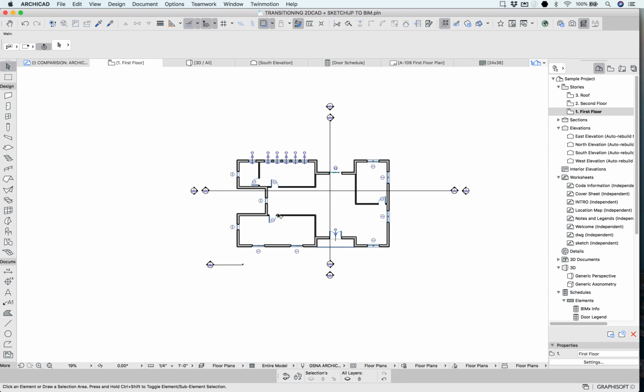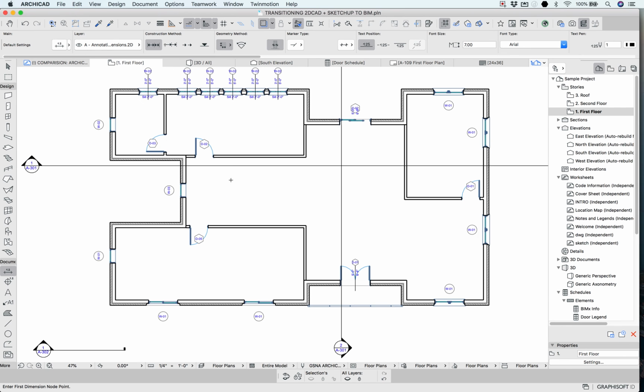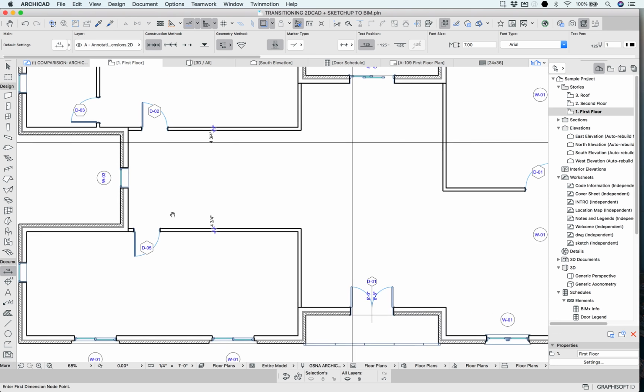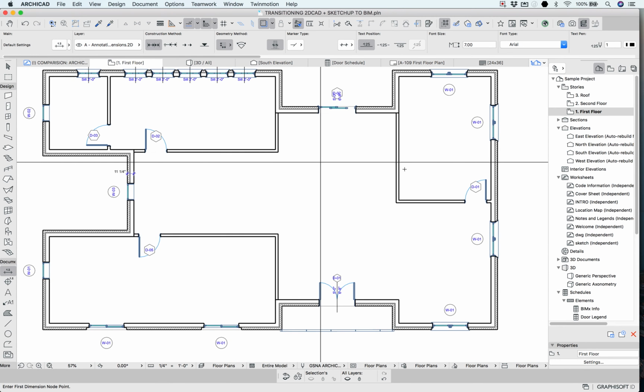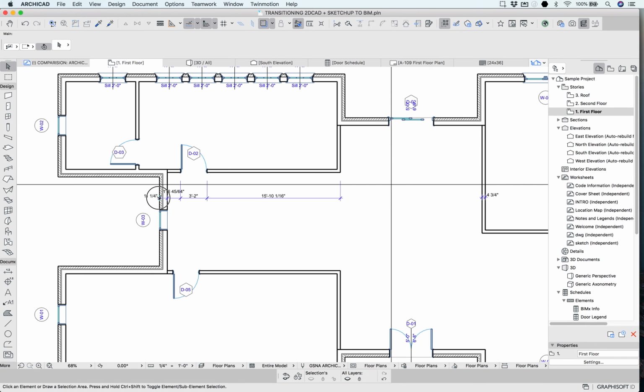So getting into our annotation, just like everything else, of course, you can go in and set up our dimensions, right? You can set up a point, you can dimension a single wall just by clicking on it if you want to, which may not be what I want to do, but I'm just saying that you can start your own dimension string. You can dimension a single point, but you can also take this dimension string and perhaps add on to it, right? So this idea of the continuous string we can begin to develop in this fashion based upon where we click on the structure. And that's always a possibility.